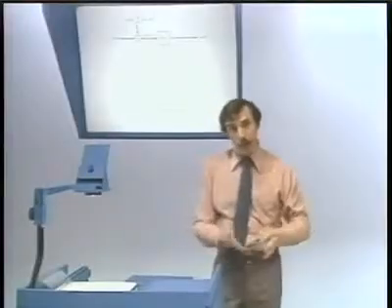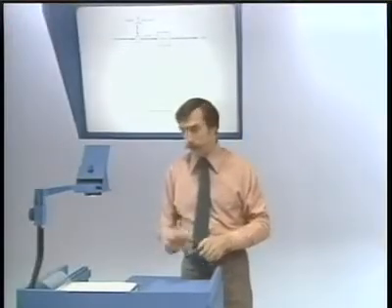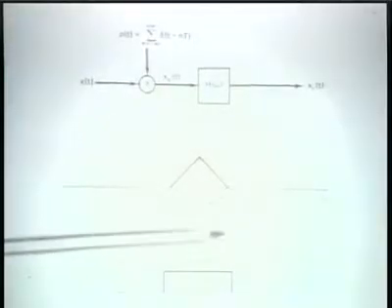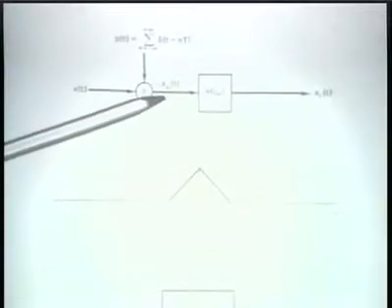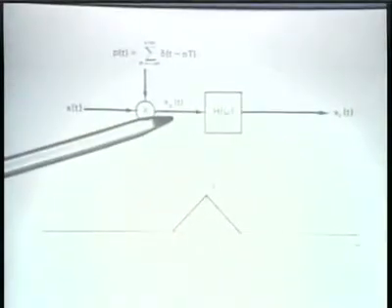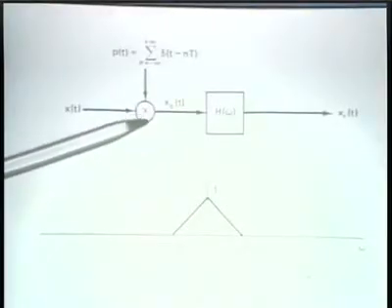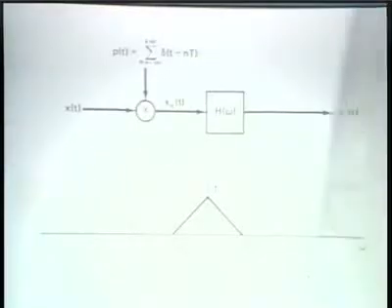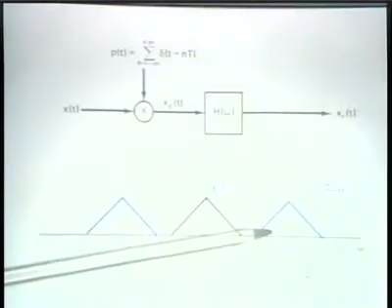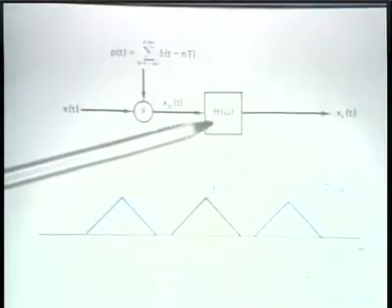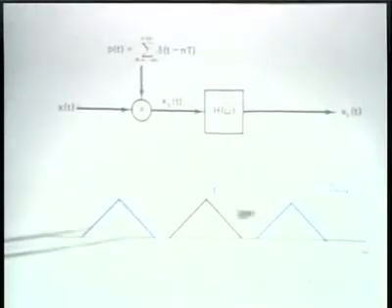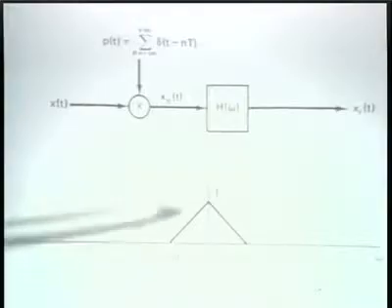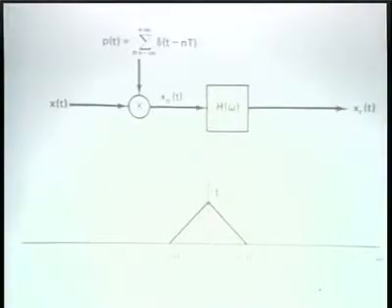And finally, to remind you of the argument once more, if we have an original signal and we have its spectrum, when we've sampled it, this is now the sampled signal, an impulse train whose instantaneous values are samples of the original waveform. The spectrum of that is the original one replicated, and when that is processed through a low-pass filter to extract this part of the spectrum, then after the low-pass filter, we can recover the original signal back again.